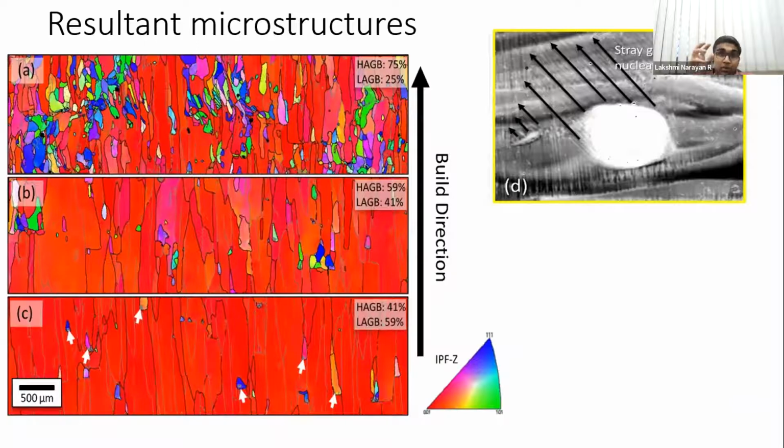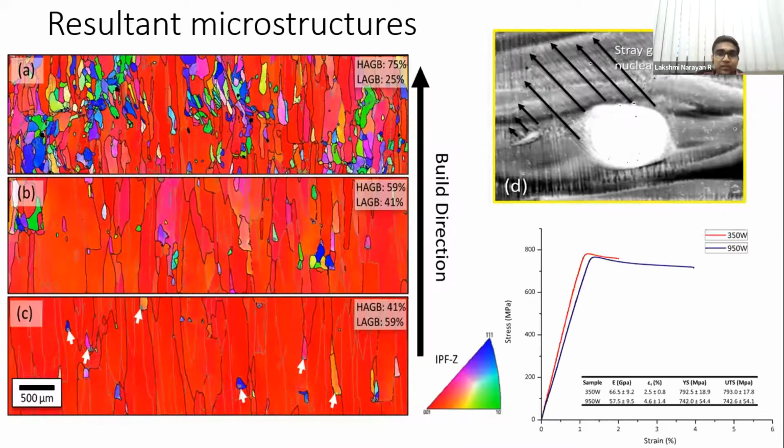Okay. So the problem of inclusion is now compounding the issue of microstructure as well. If you have an inclusion, it will essentially lead to bad microstructure also, the ones which you don't want to have. So that's why reducing the inclusion level is actually beneficial in getting better microstructure. So this is the third reason why you want to have lesser inclusions.